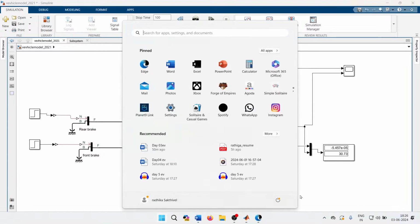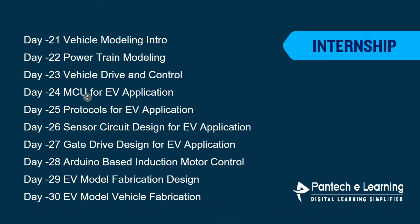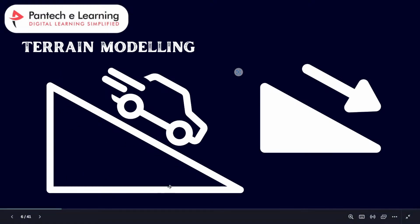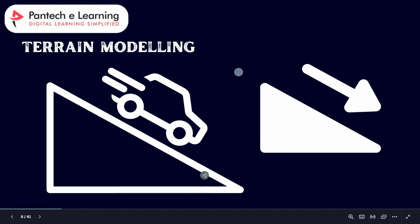So I will show you, this is the slope, right? This is our slope versus distance values. Initially our vehicle is at 0 position, after we apply the negative values. Whenever our downhill slope is applied to our model, up to 10 seconds, we are applying 2 brakes in this simulation. So here one brake and here the second brake.